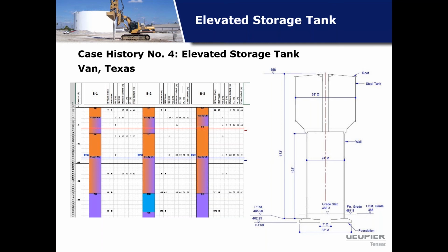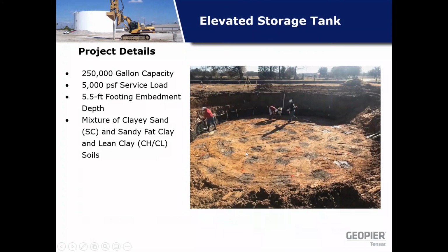Typical profile, and a construction area of the same storage tank after we install the Geopier. What you see in gray color are the locations of individual Geopier elements. So we installed the piers from the existing ground surface, and then the contractor followed us. He over excavated the area. Minor grading was performed, and then you're ready to cast reinforcement and footings to support this tank structure.